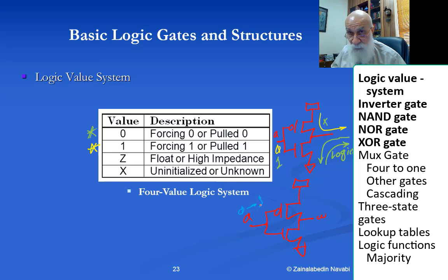But when it changes to 1, the lower transistor reacts quicker, so there will be a 0 coming here, whereas the upper transistor, because of the 0 on the A input, still has a path to the output, and therefore momentarily, for a very little amount of time, both the upper transistor and the lower transistor will be driving.